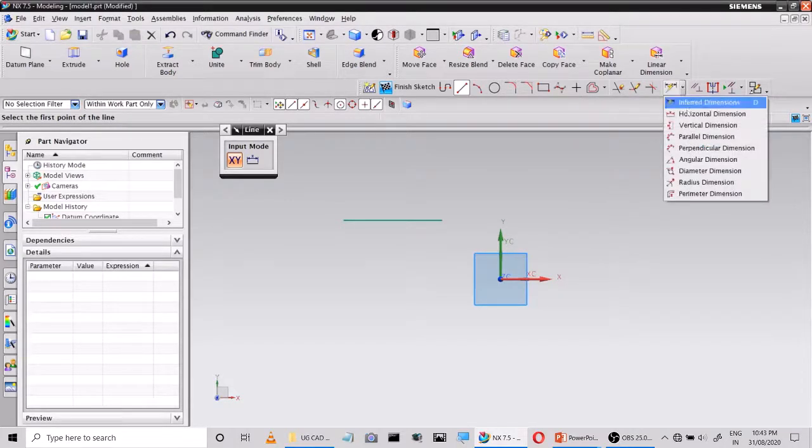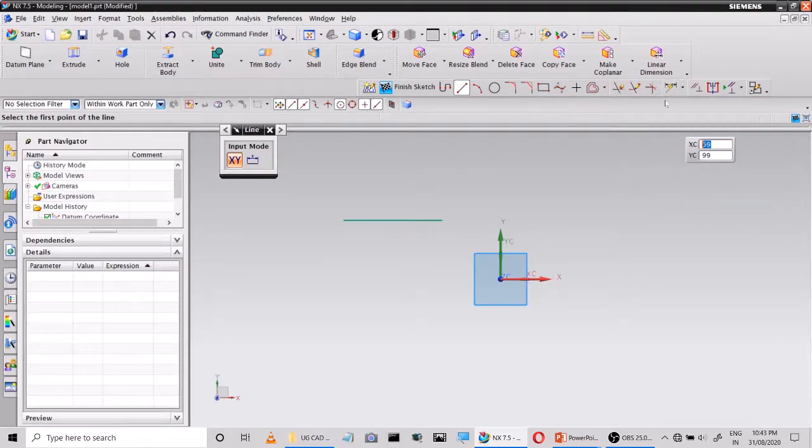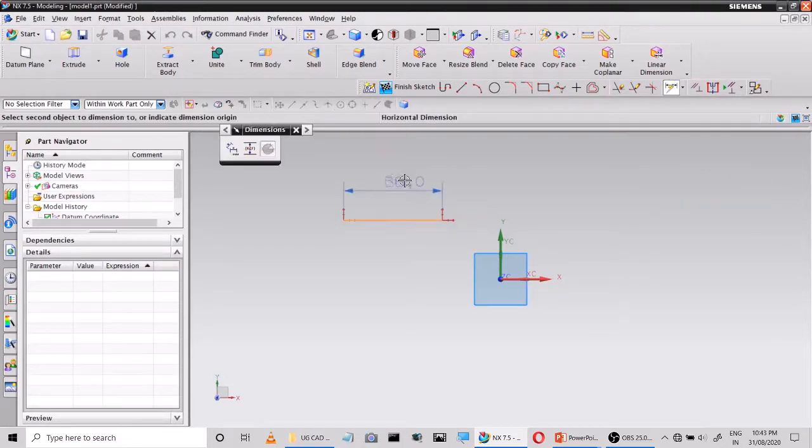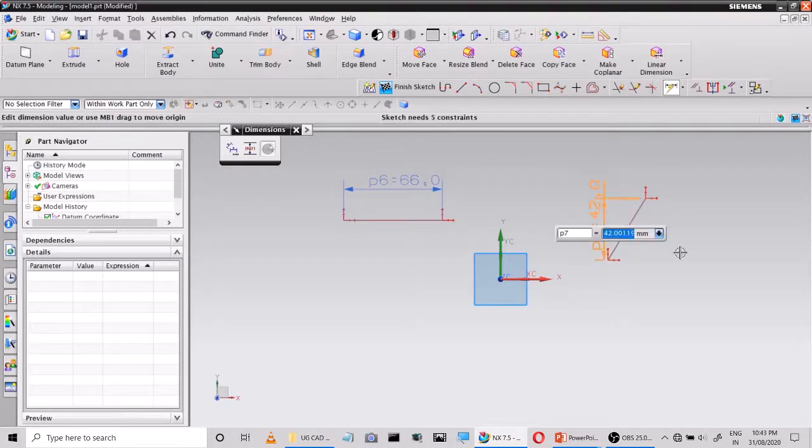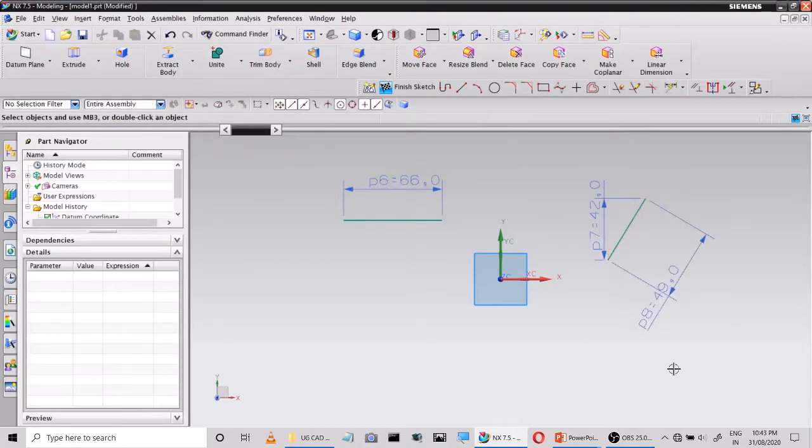Now if you want to get the exact required dimensions, you click on this chevron. Now inferred, so it will automatically take what type of object you have drawn. With respect to that one, it will take automatic. Suppose you want to get the required one, for example, just observe, first initially it went for vertical dimensions. If I click one more time, it has gone for parallel dimensions, right?